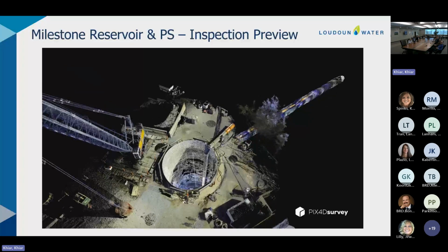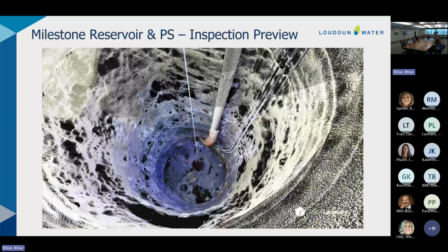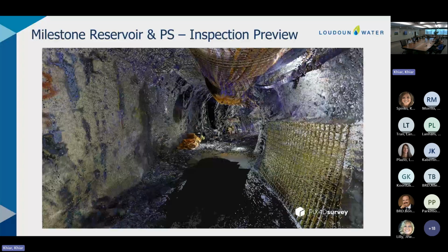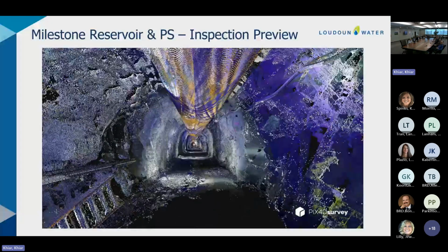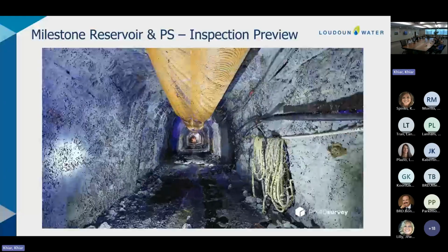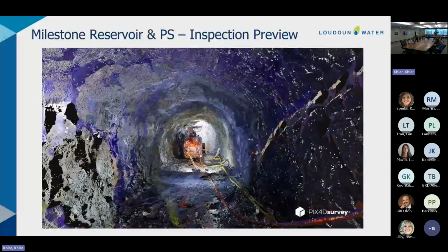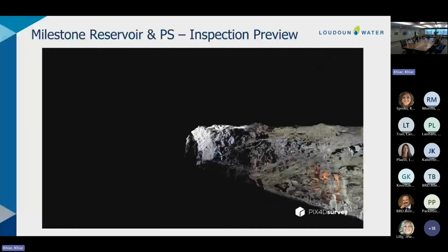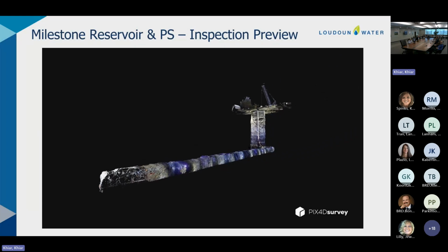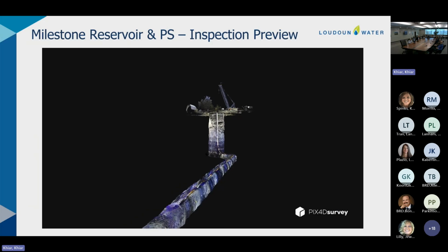This is data collected by Schnabel, our inspections service provider in charge of all geotech inspections associated with the project under our RE contract. And it basically consists of, I guess it's safe to say, millions of points gathered in space using LiDAR. As we excavate the tunnel, we collect this data to retain good information on the quality of the rock, the alignment, subsurface conditions, any faults that we encounter.